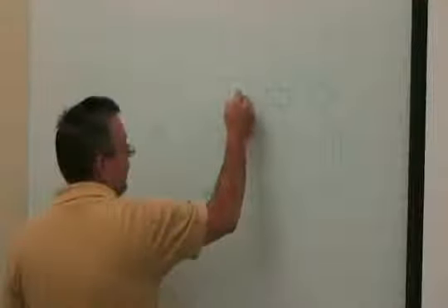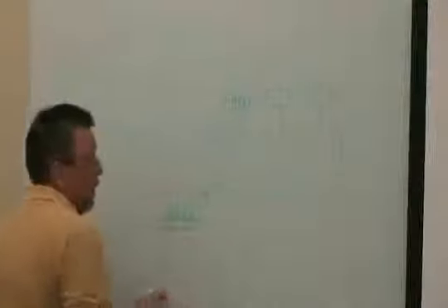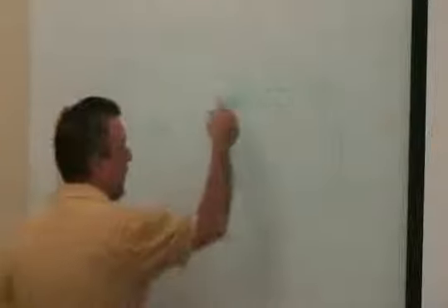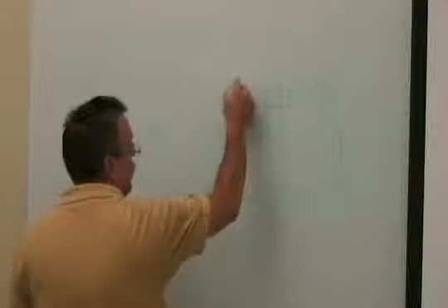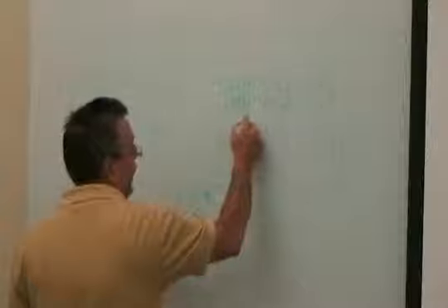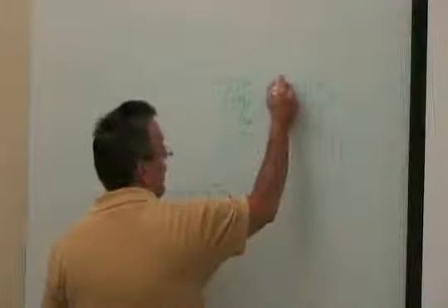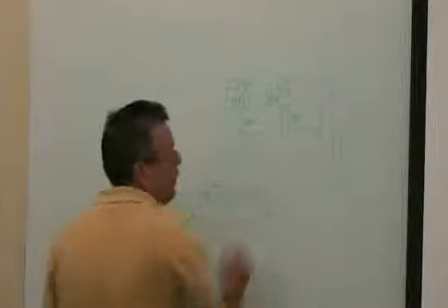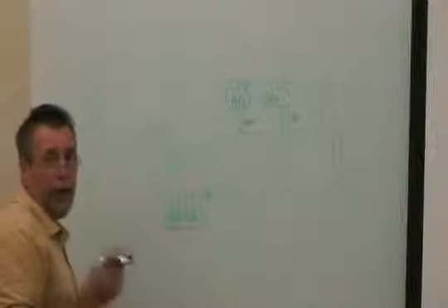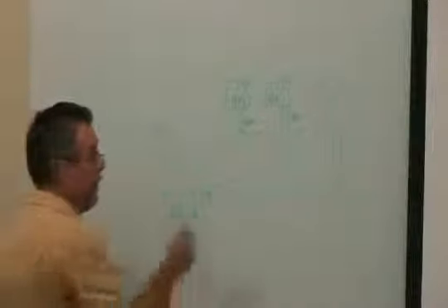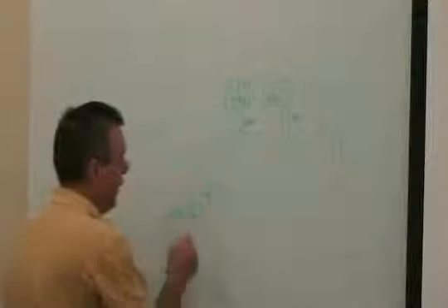And if I'm in the heating mode, that means the compressor is actually absorbing temperature out of the loop. So I'm coming in at 70, going out at 60 or 67. If I'm cooling, I'm coming in at 70 and going out at maybe 78 or 80 in the mild season. So you can see if you've got simultaneous heating and cooling, you don't necessarily need any heat rejection or heat absorption.